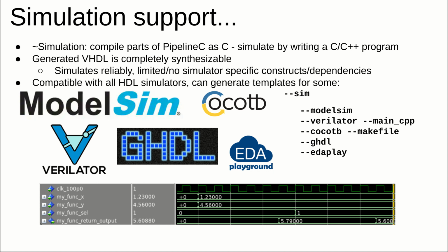It doesn't use any weird simulation-specific constructs that wouldn't synthesize anyway. It generates templates for some of these tools listed here, and you see some of the command lines over here on the right. At the bottom here is what we got to opening up ModelSim in the earlier example. ModelSim opened, and I just went in here and forced a few values for you and clocked the clock, and you can see the 5-cycle latency. It works that easily.